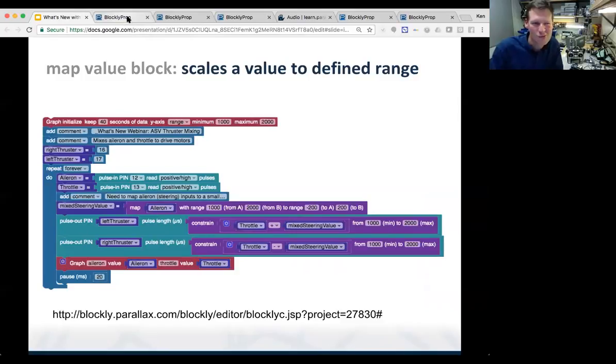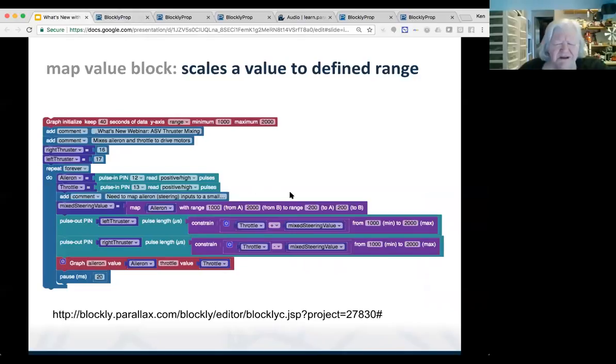Excellent. What it shows though is on a lot of RC radios, if you want to reverse direction, you have to send it a couple different codes. And that's in there so that you can use the RC radio exactly like an RC radio with the ESC that comes with radio control equipment.